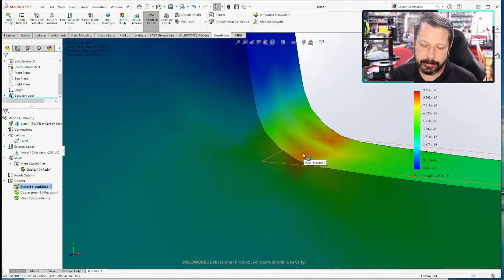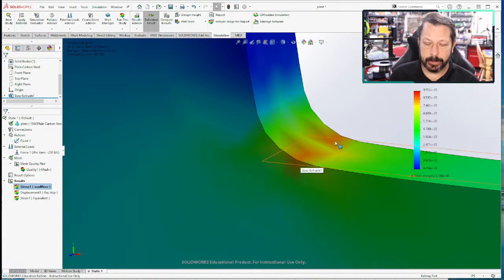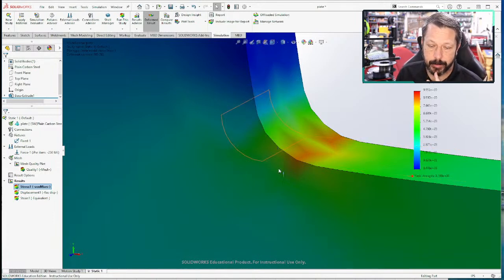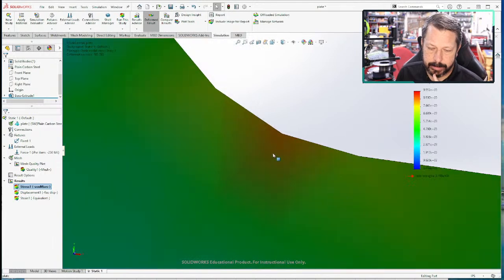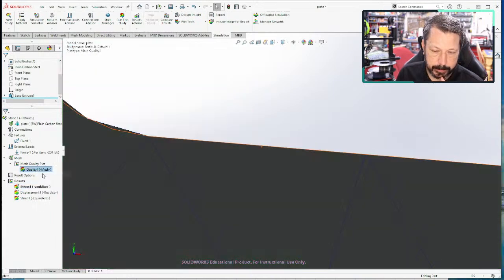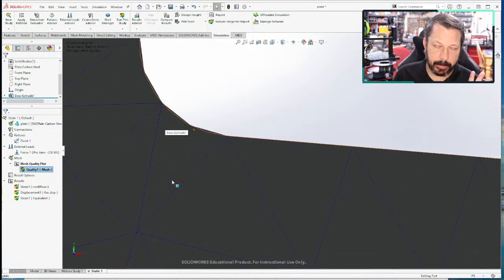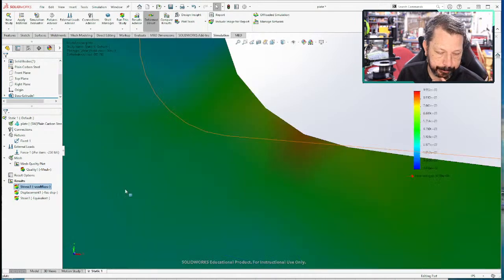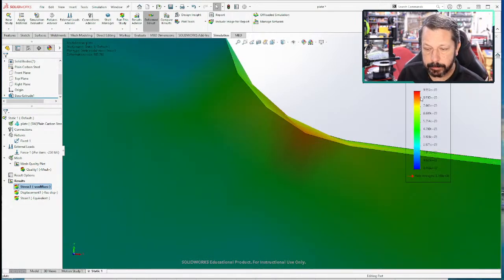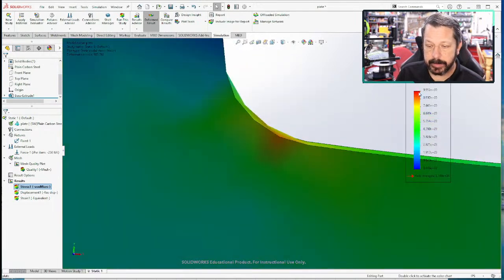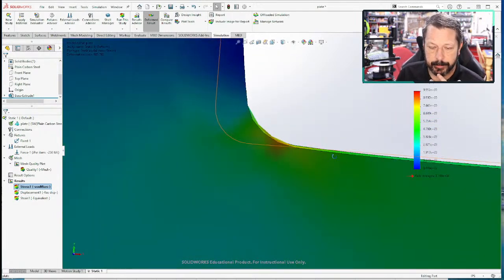And so I typically kind of ignore the highest stresses that are shown on one of these type simulations and look around there. So, what am I getting, kind of around somewhere here? And yeah, I've got some reds deeper into the model. Again, I don't have that many elements in here. There's like one element controlling that whole curve there, from there to there. So I don't have that many elements to work with. But those numbers are in the range of what I expect. And even the very peak number is not that far off. It's the same order of magnitude.